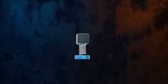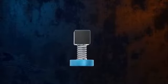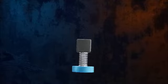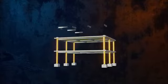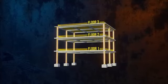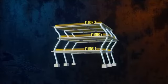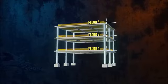Single degree of freedom models are really useful, but sometimes the dynamics of a system are better modeled using multiple degrees of freedom. Say we want to model the dynamic response of a 3-story building. If we assume that the columns between the floors are axially rigid, but can bend laterally, we can model it as a system with 3 degrees of freedom, the x-coordinate of each floor.